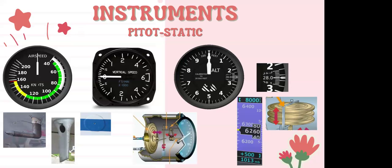So we have ourselves as the aircraft moving through the air. That's called dynamic air. We also have the ambient air around us. When I say ambient air, I mean the air sitting as it is, undisturbed, at whatever pressure and altitude we're at. Ambient, right? That is measured through the static port. That has nothing really to do with our speed. It really just has to do with the air surrounding us.